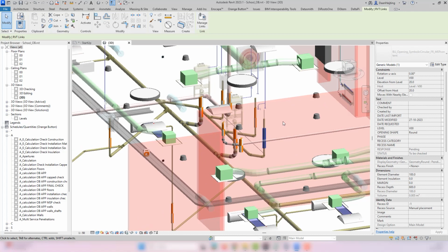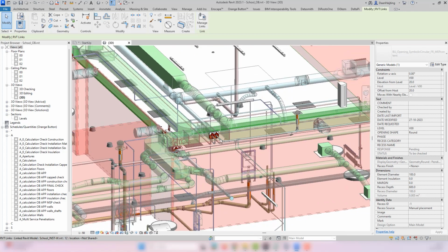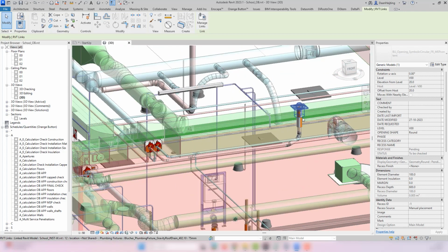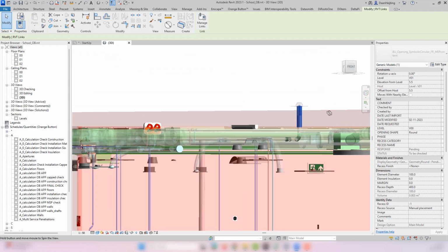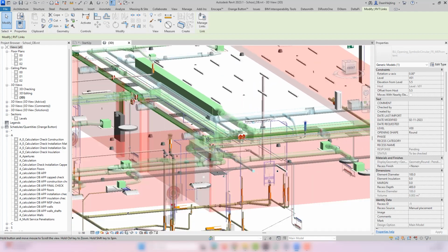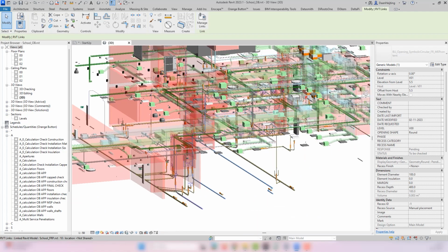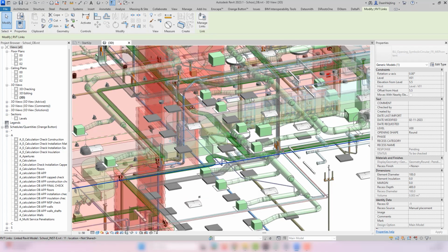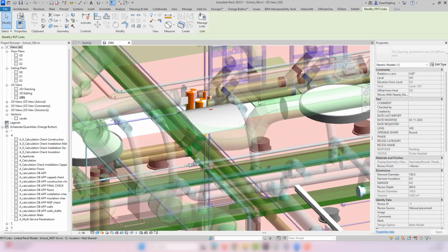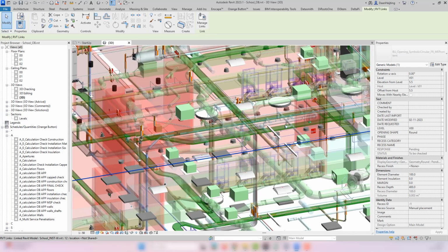More and more openings are modeled in the BIM environment as a physical BIM object. Most of the time, these openings are also planned for execution by the general contractor, leaving no space for optimization based on the selected Firestop solution. For instance, if you use a filler, you will need a smaller opening than if you would use a mineral fiberboard solution.